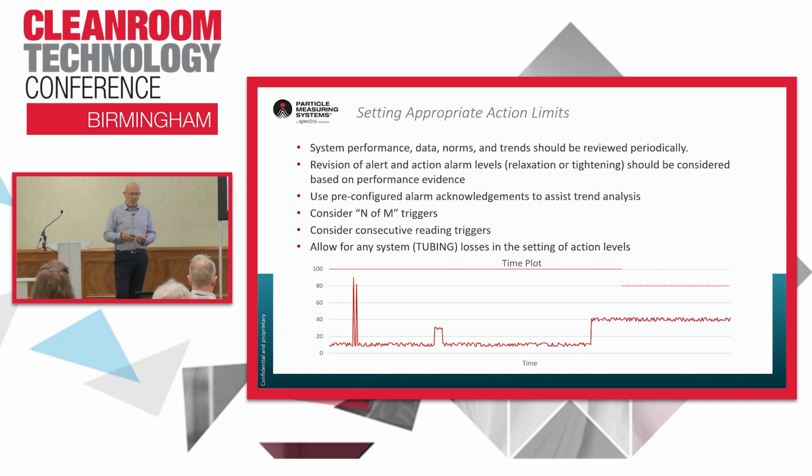Use of pre-configured alarm acknowledgement, so that helps trending. If we allowed free text, I'm going to type in cleaning. Morgan, from his talk yesterday, is going to type in spray and pray. But if we've all got a drop down and it's prescribed text, then that helps us trend the alarm causes where we know it.